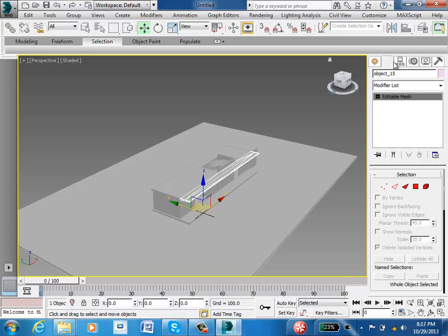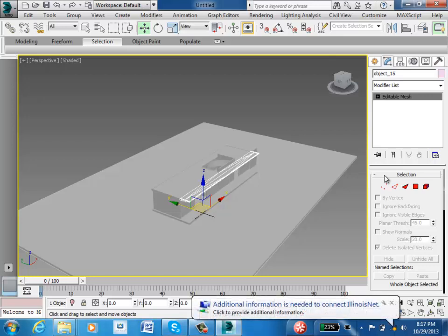It's a modifiable mesh, and you can see that over here when I have the Modify tab open, it's giving me a whole series of options on how to modify that object. The best thing to do, since we won't be covering modeling in this, is if you need to make a change, make the change in Rhinoceros and re-export the object. The world origin will stay the same, so you won't have to move it into place, assuming you haven't moved the original model. So what I tend to do is if I make a big change, I'll delete some objects in 3ds Max, and I will re-import those objects alone from Rhino into 3ds Max to take their place.